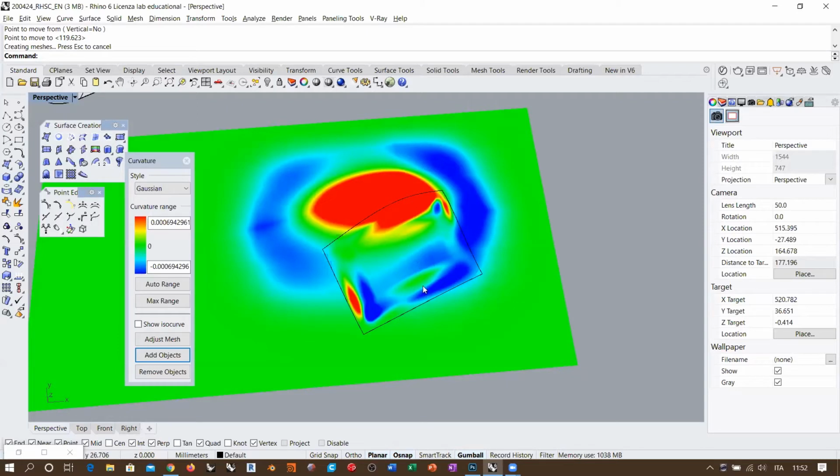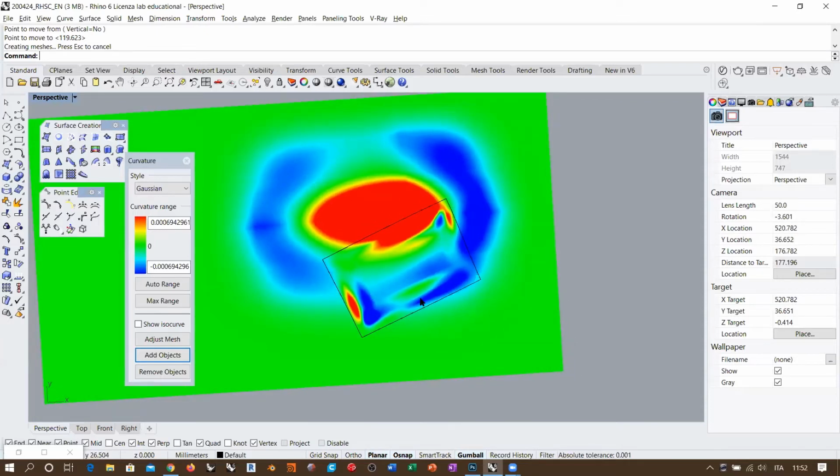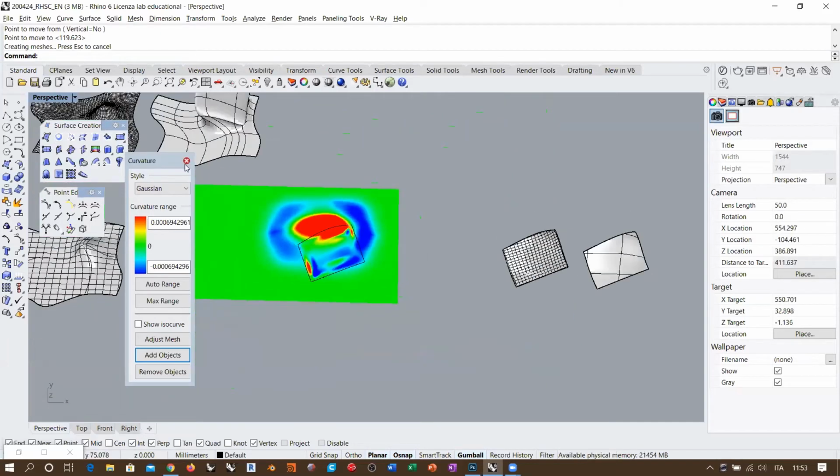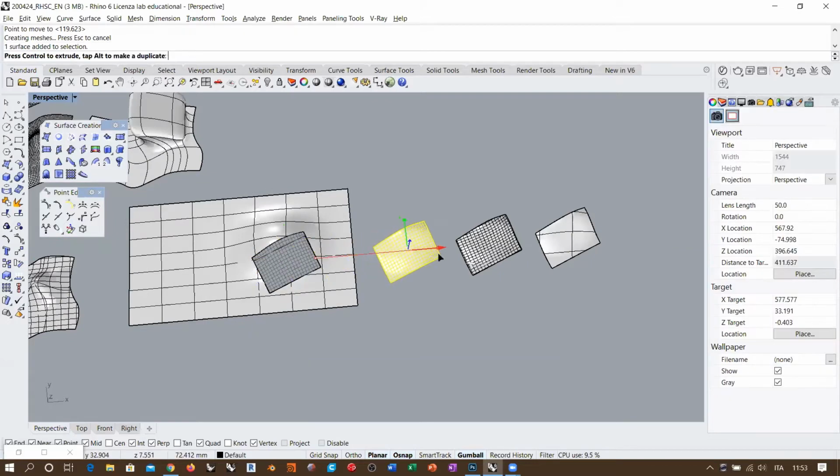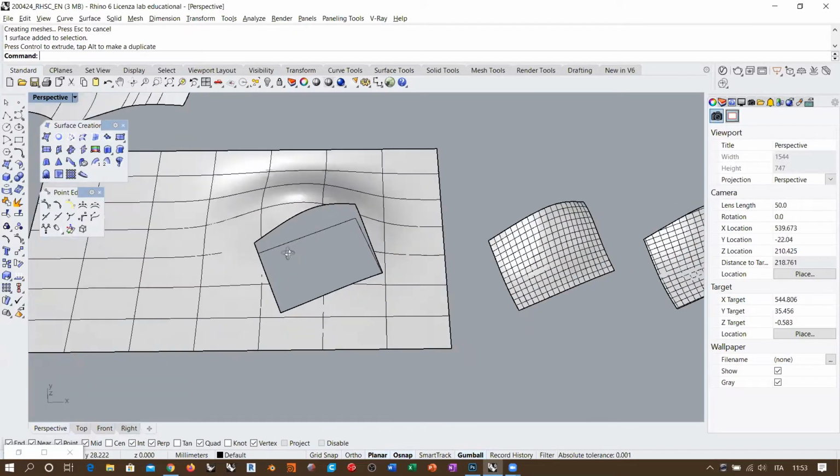So the behavior in the inner part is always the result of an interpolation. So it has nothing to do with the original curvature of the surface, which should not have this kind of noise in this area. It should only have some gradient like this one on this part, okay? So no matter how you rebuild this hole here, you are always going to get some weird behavior.